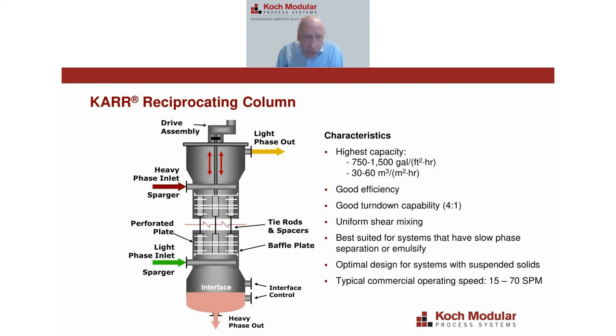And we've even seen cases where in the laboratory you emulsify so easily that you can't really handle the system, but we can still do that in a Karr column because there's something about this countercurrent flow and this reciprocating mixing action that allows us to operate with those types of systems. We can also handle solids; we've run up to 40% solids through a Karr column, and that's because, as I'll show you in a minute with what a plate stack looks like, it has a lot of open area and there are no stationary plates or anything inside this column.